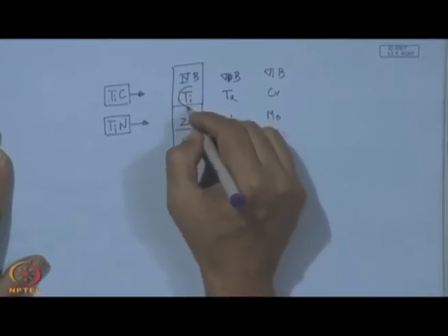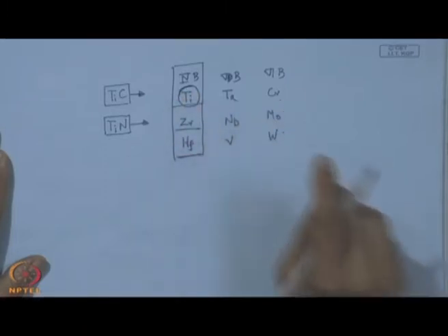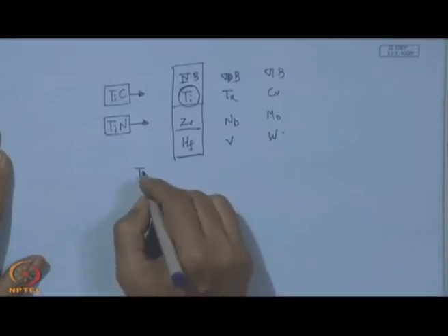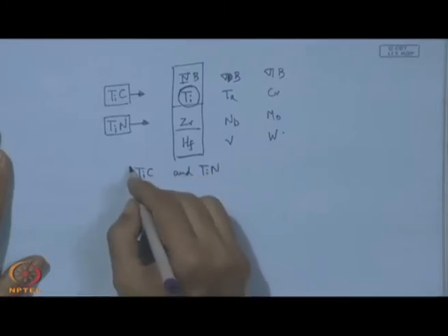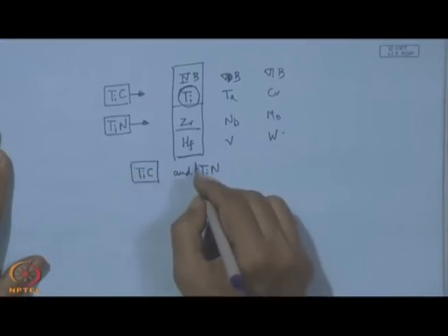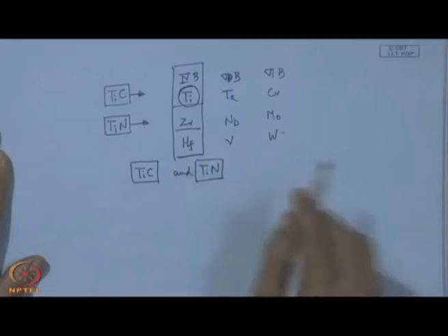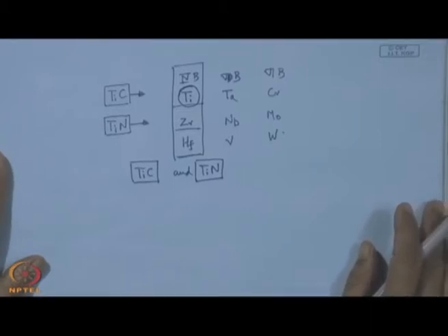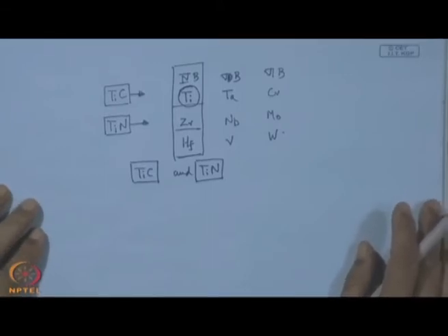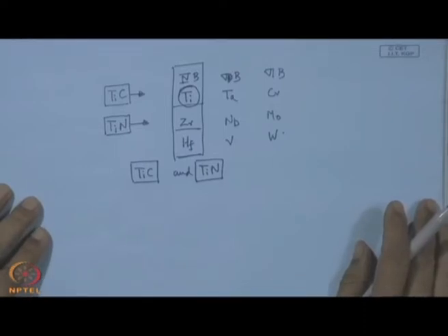If we now choose titanium as one of the strategic materials, in that case we have TiC and TiN having their well defined domains of application, but there are situations where we may need a balance of properties between titanium carbide and titanium nitride. That means, the functional surface needs both resistance to abrasion and resistance to adhesion.